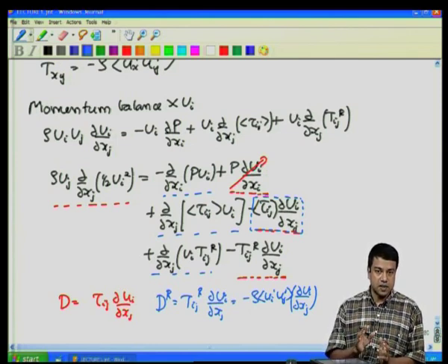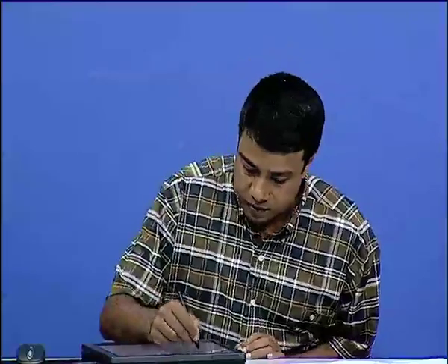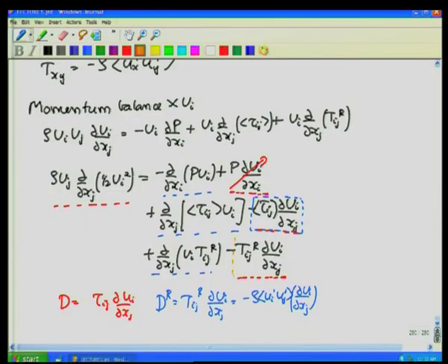However, the flow is at steady state, and at steady state there has to be a balance between production and dissipation. What that implies is that the dissipation of energy in the mean momentum conservation equation due to the Reynolds stress is much larger than molecular diffusion. Therefore, in the energy conservation equation, the dominant diffusion is due to the Reynolds stress term. That is what is balancing the production of energy due to the mean flow or due to the mean pressure gradient.